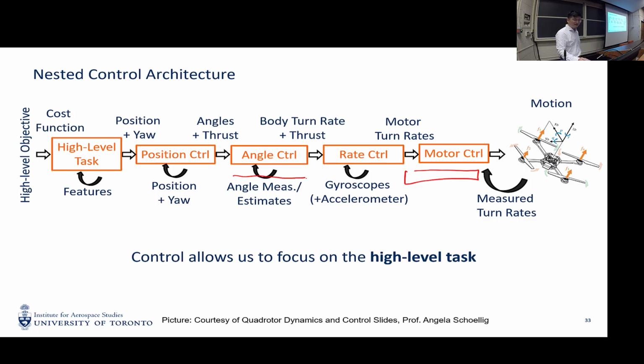And on top of that, in order to control the angle, where the quadrotor points, we need to control angular velocity by varying the speed of each rotor, such that it creates different thrust, resulting in different moments to rotate the quadrotor. Once we have the angle control and angular velocity control, we can control the lift. So we can assume that there is a force in 3 dimensions that we can assign arbitrarily.